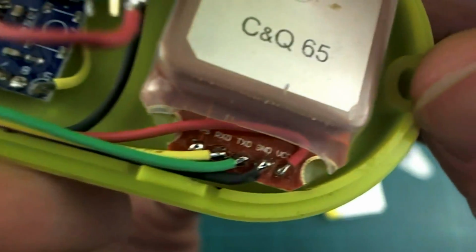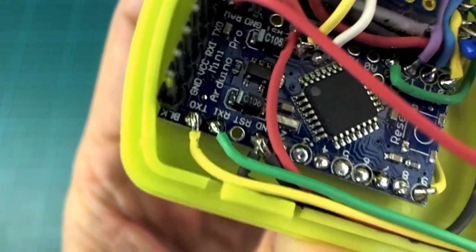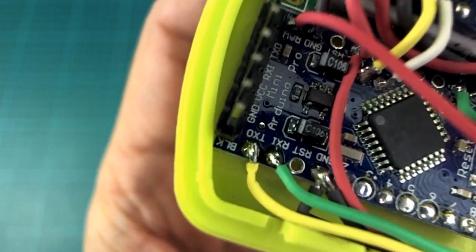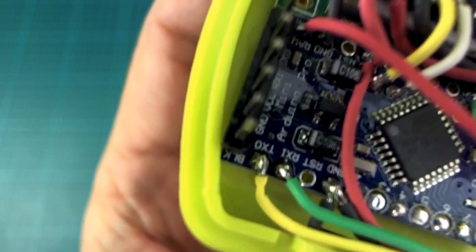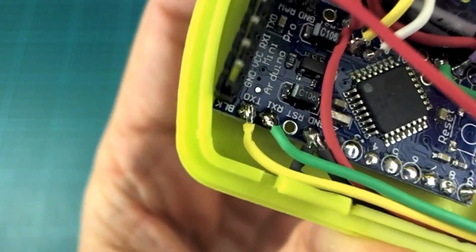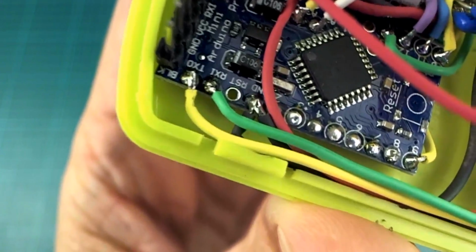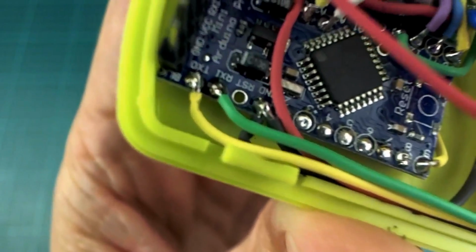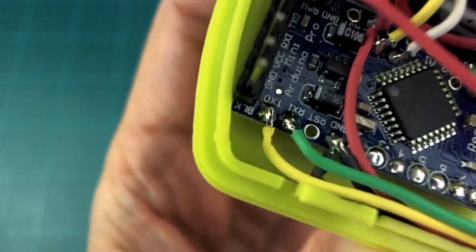And this GPS module I have runs quite well off 3.3 volts, so I've been able to just connect this directly to my Arduino VCC for power. And you'll notice that it's going on to the RX and TX pins of the Arduino, so it's using hardware serial, and that's necessary to get the data in from the GPS fast enough. If you use software serial, the data just comes in very intermittently. It's not very reliable.